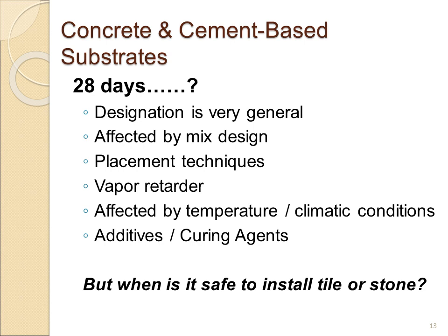When we think of manufacturers' instructions, some of these instructions, for example, when we talk about concrete, having to cure 28 days, that's a very general designation. As we see here in the list, there are many things that could affect concrete that could extend cure times, such as placement techniques, how much water is used, whether there's a vapor retarder underneath the slab. And when we think about additions to older buildings where trenches are cut and vapor retarders are damaged, all of these are going to affect how much moisture is going to come through in that particular area.